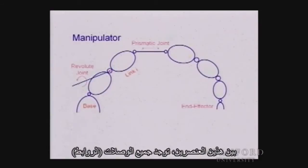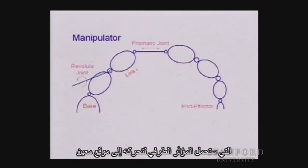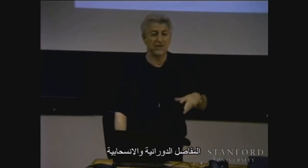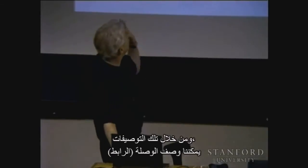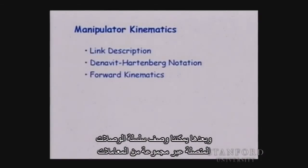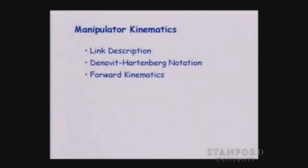And between these two objects, you have all the links that are going to carry the end effector to move it to some location. And the question is, how can we describe this mechanism? So we will see that we are using joints, different kinds, joints that are revolute, prismatic, and through those descriptions we can describe the link, and then we can describe the chain of links connected through a set of parameters.